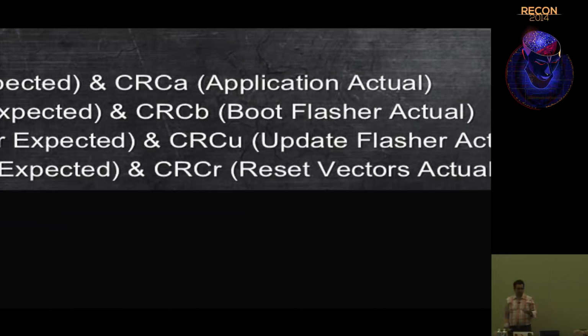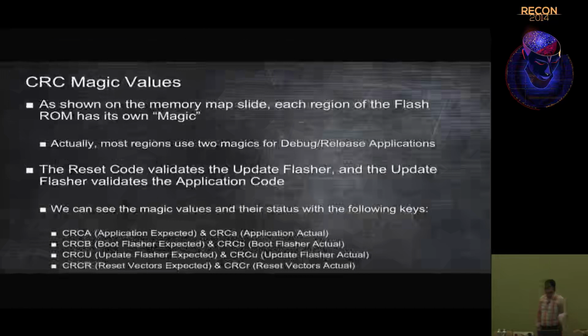So the first thing I did was, OK, it's telling me what checksum it wants and what checksum it computed. Let me just update my binary file with the checksums, and then it'll flash. But I also wanted to know, what are these checksums? Because they say CRC, but they're not actually CRC. Like, I've tried every CRC 16, 32. They're not actually CRC sums.